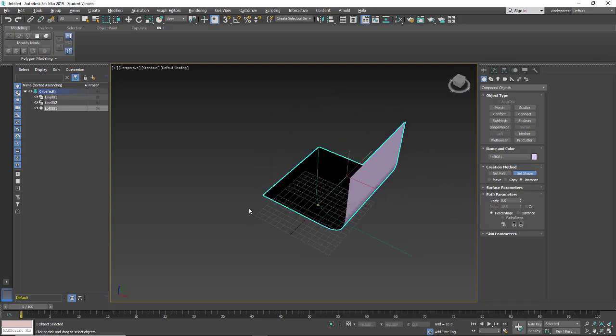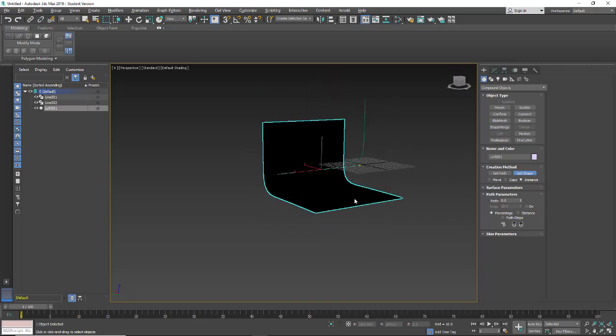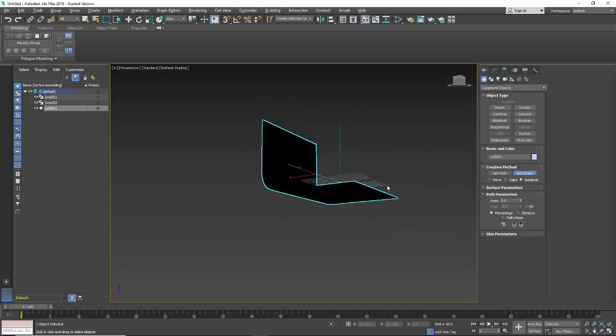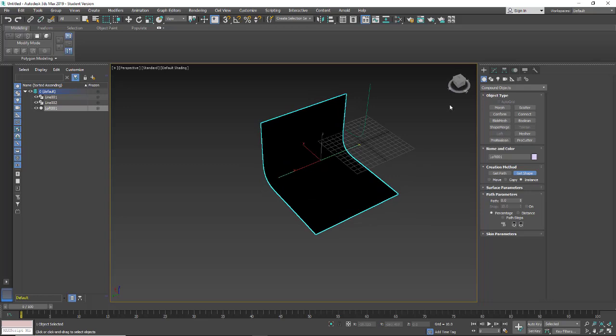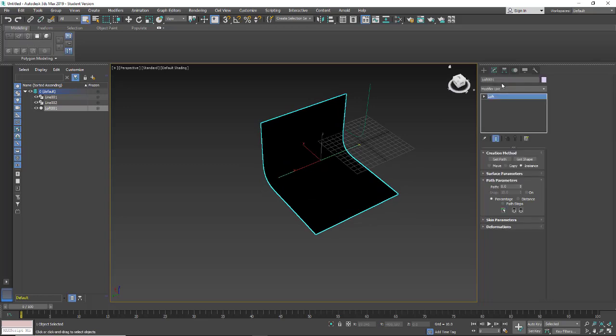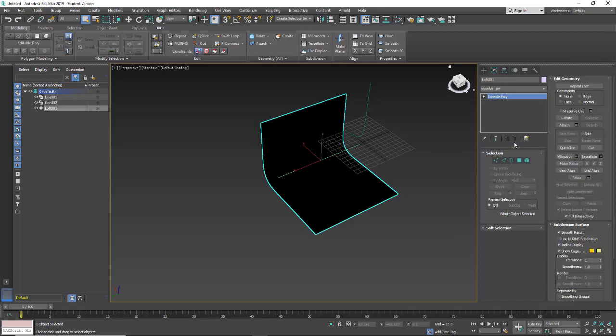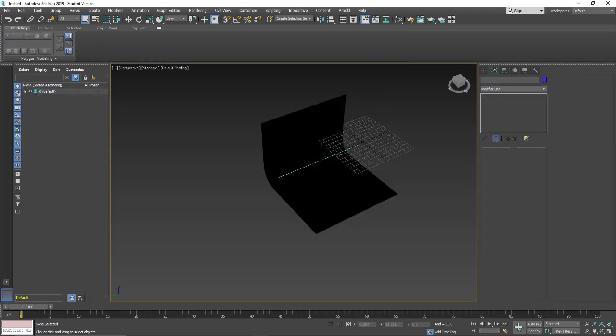So we can rotate this, but it has made it backwards, and it tends to do that all the time with this shape. So what I'm going to do is go underneath the Modify tab and take the loft, right click, and I'm just going to make it an editable poly. Now I'm no longer associated with these lines, so I can delete these from my scene.